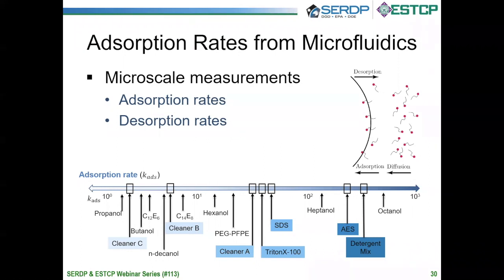If you think about what actually has to happen for droplets to destabilize, something like coalescence, if two drops come together, there's this thin surfactant-laden film between the 2 droplets. And that film has to thin and dimple and then rupture and break in order for the drops to come together and coalesce in the treatment process.